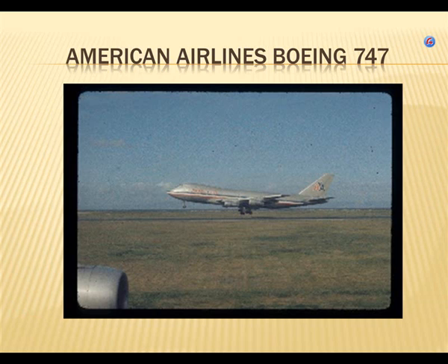So here's an Americanized Boeing 747 some years ago, and you can see that for significant aerodynamic reasons, the tail is huge, isn't it? Huge. It's because they need the ability to keep control of the yaw of the aircraft. And of course, the bigger and heavier the aircraft, the more tail surface you need, unless you're a fighter plane. If you're a fighter plane, all bets are off, because fighter planes operate kind of in a bit of a different realm of aerodynamics.